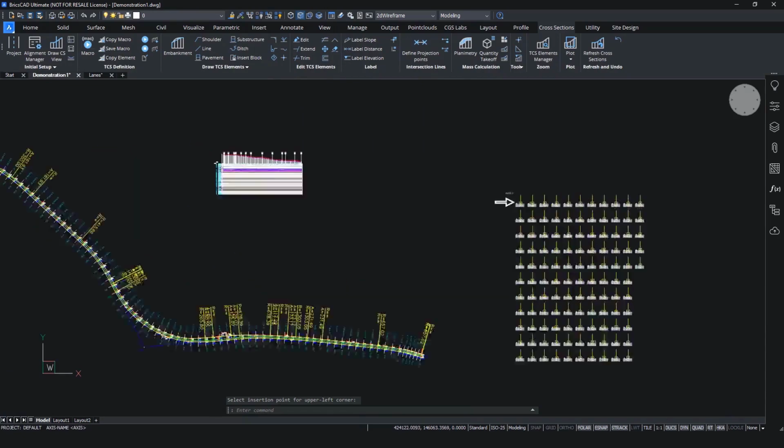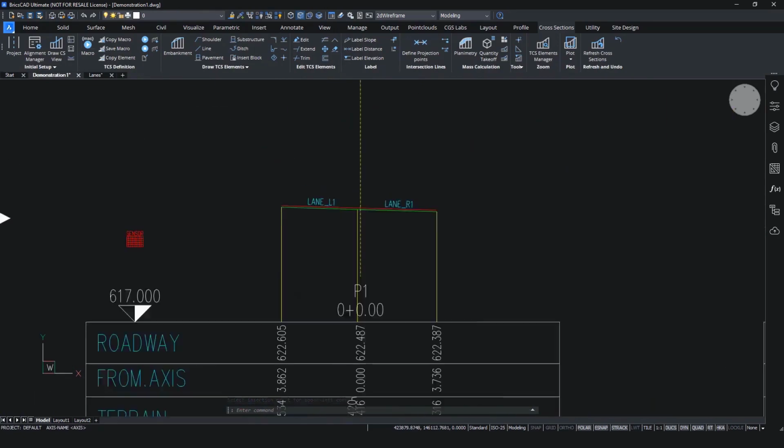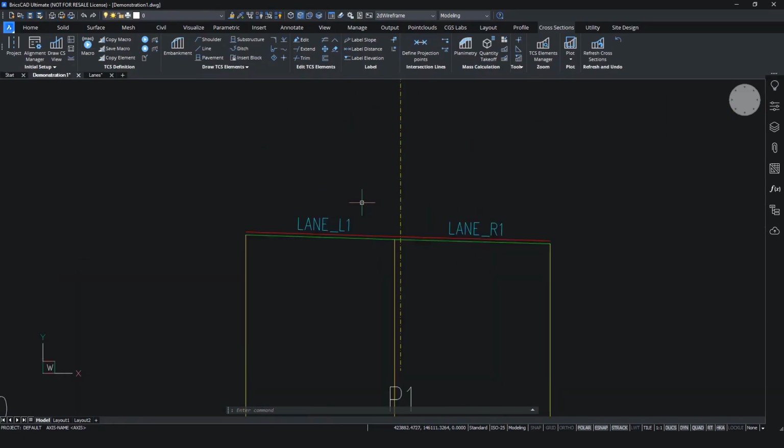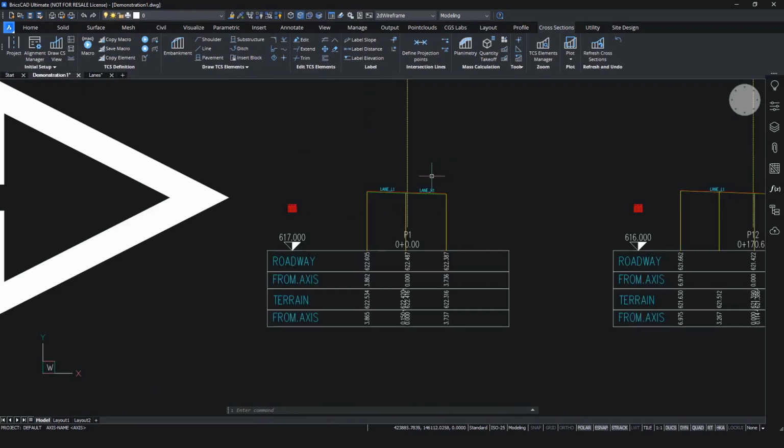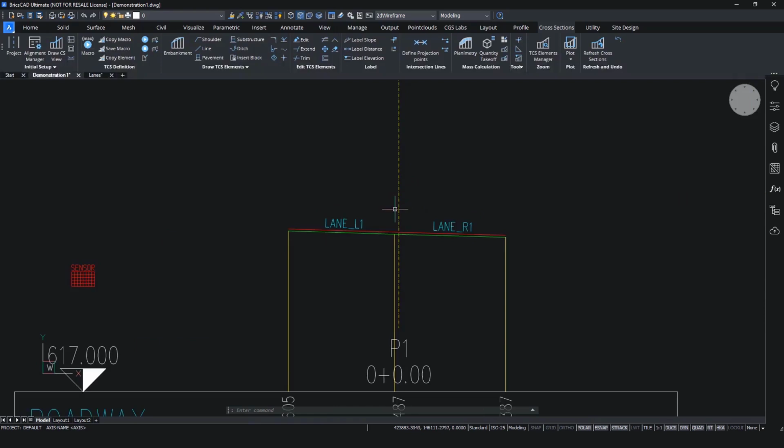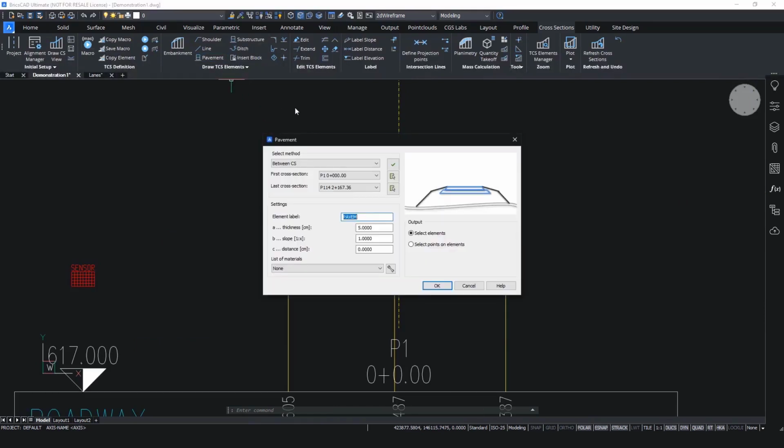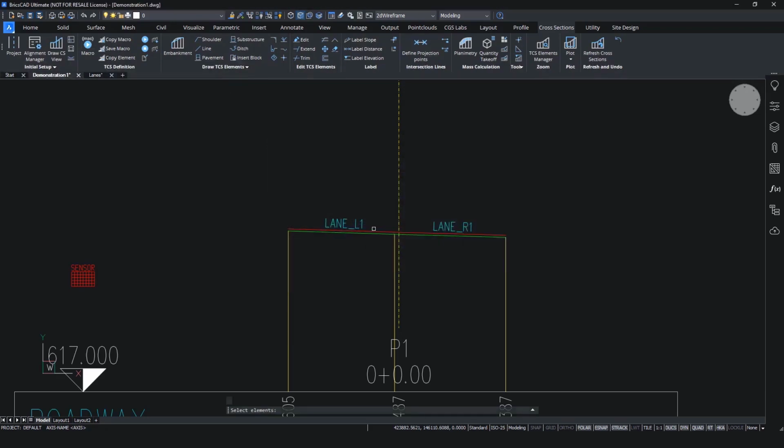And let's take a look. And we also get the road height and the super elevations. So we can use that to draw other elements. So we can make some pavement elements. For example, the first surface layer, I will use the surface course material, or I can make our own and define the thickness of the layer.